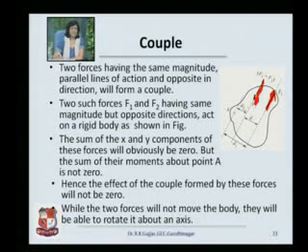So therefore we can say that these two forces combined together will not be able to move the body either in the x direction or in the y direction, because the x and y components are negating each other. But because of the couple that is being formed by these two forces, they will be able to rotate the body in a particular direction. In which direction they will rotate is very simple to understand by taking your right hand thumb and finger. If you look at these two forces, this particular couple is trying to rotate the body in the anti-clockwise direction.